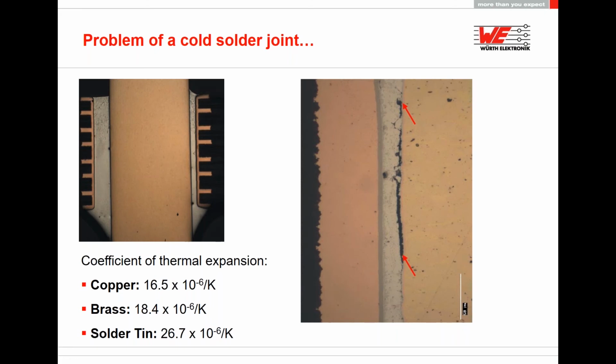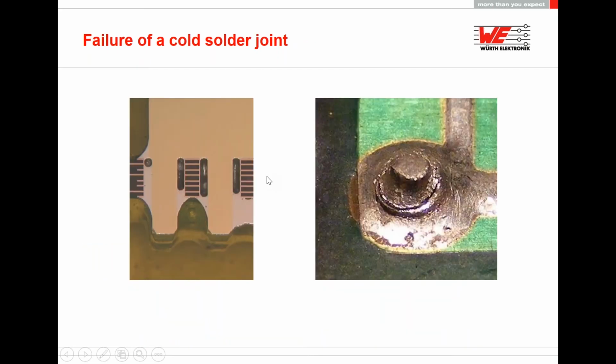So from my experience, we say that soldering technology is limited at about 100 amps, and everything above is quite dangerous to solder because of a lot of thermal expansion during the lifetime, and also it's difficult to control the solder joints, also in the SMT solder joint or in a THT or THR solder joint.